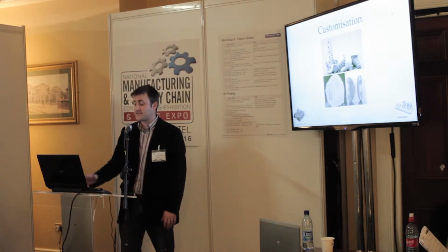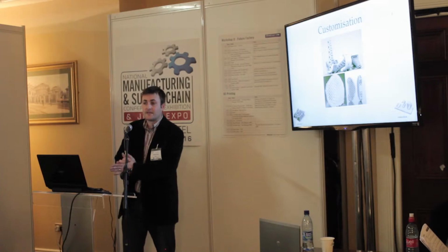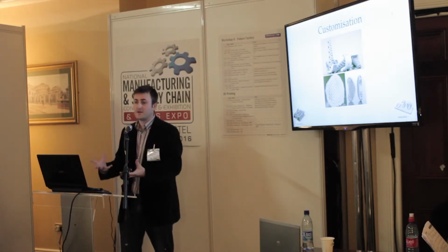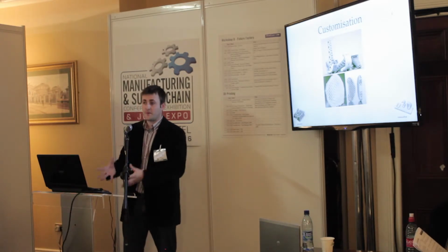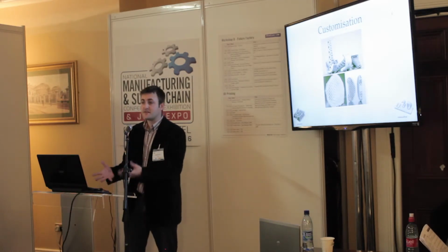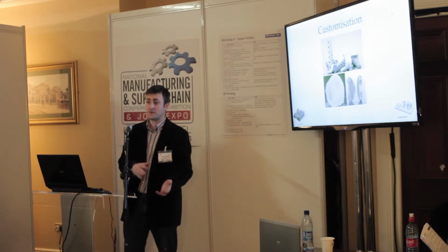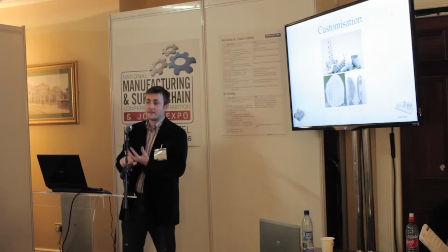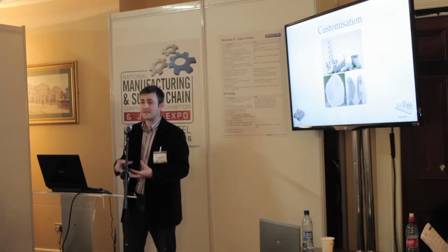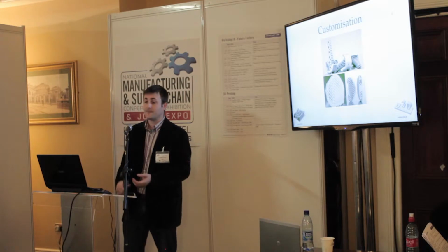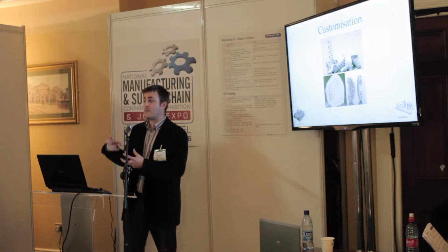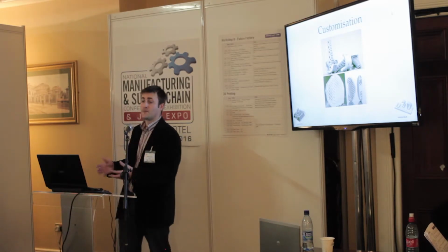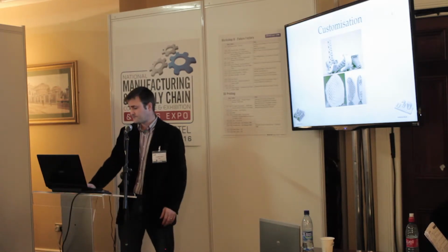Also, specifically with customization, medical implants are hugely benefiting from this technology. First of all, you can customize the component to the person. Every person is different, every injury is different, so the implant should be customized to them. Secondly, you can increase the surface area, you can make the parts hollow. This allows, in these sort of hip implants and knee implants, for greater area for the bone to knit onto the parts, and also it allows for increased blood flow, which improves the recovery of the patient.